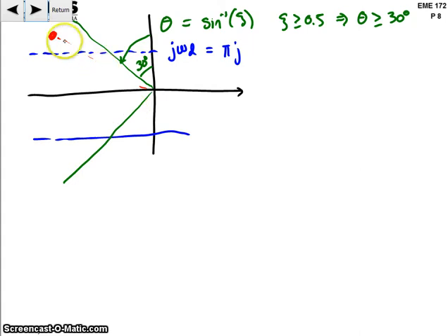Okay, and so clearly it is for any pole that falls below this green line. So the allowable region for the poles is in here, okay, and in here, right? Remember, they're complex conjugate pairs. So these are the allowable pole locations that I shaded in yellow, okay?